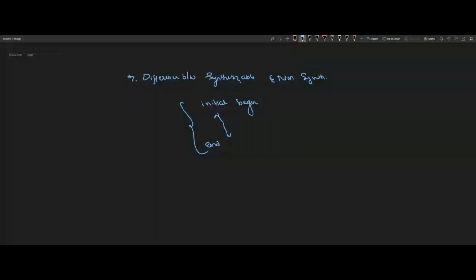Using a counter. Right. So we should know what the clock coming in is. For example, if a 40 megahertz clock is coming as the input, internally, can we use this clock directly? We can use it, but what is the issue actually? This is an external crystal, and from there you are getting 40 megahertz. So this is my scenario. Can you suggest how you are going to handle this clock and generate a 10 millisecond delay?